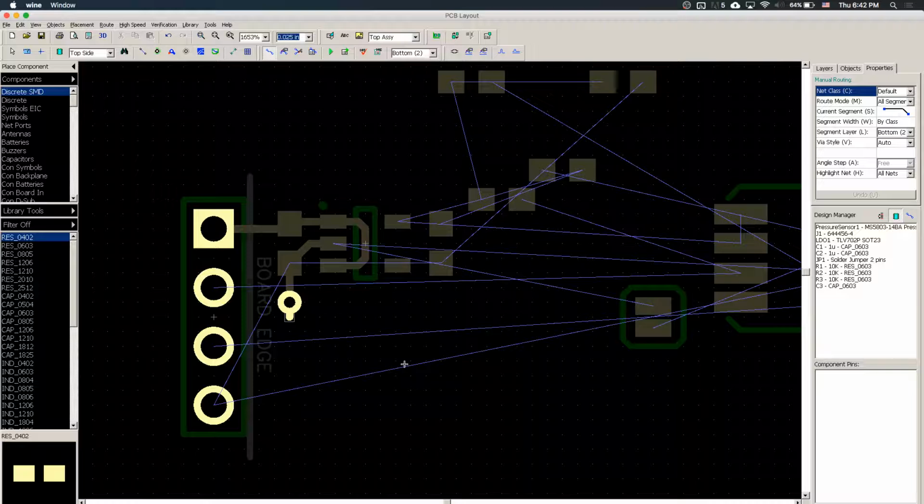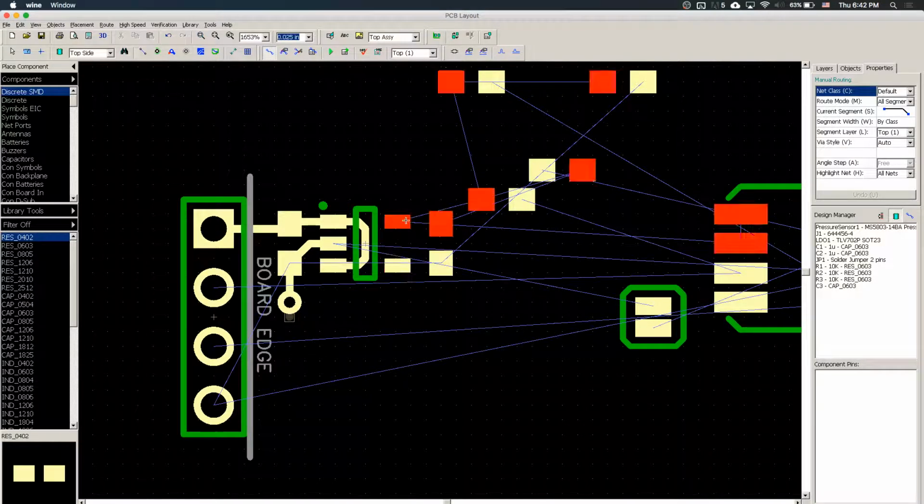Should we try and limit the amount of wires we have on board? Yes, you should try to limit the amount of wire on board. But for ground plane, it's better for you to use a via because that's the easiest way for you to connect to the ground, and that has the lowest resistance compared with the other method. All right, so our ground to here.